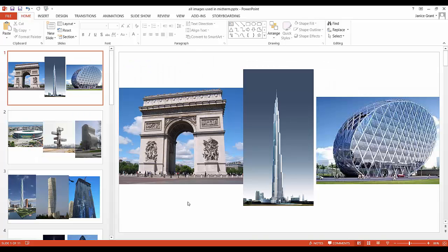So when you look at these forms, you can think about creating a mass model and using reference planes to draw on the face of that reference plane. So here in this example, there is a vertical reference plane. That line and this ellipse can be created on it, and then use create form to create your shape.